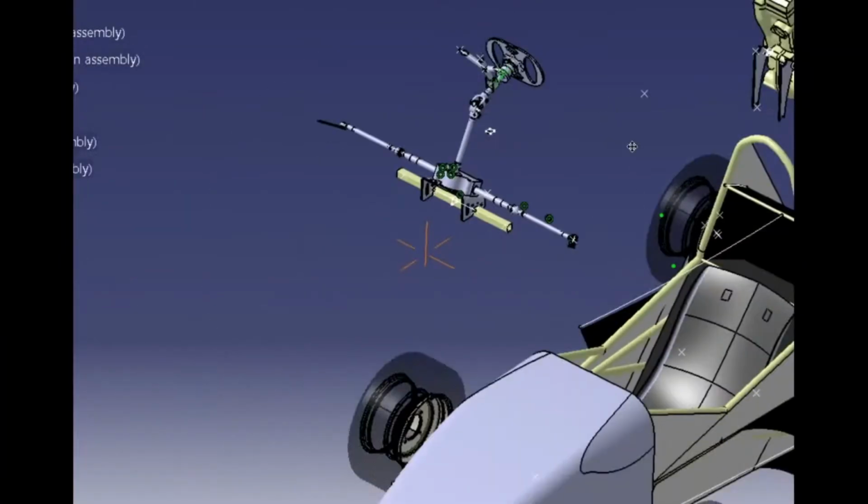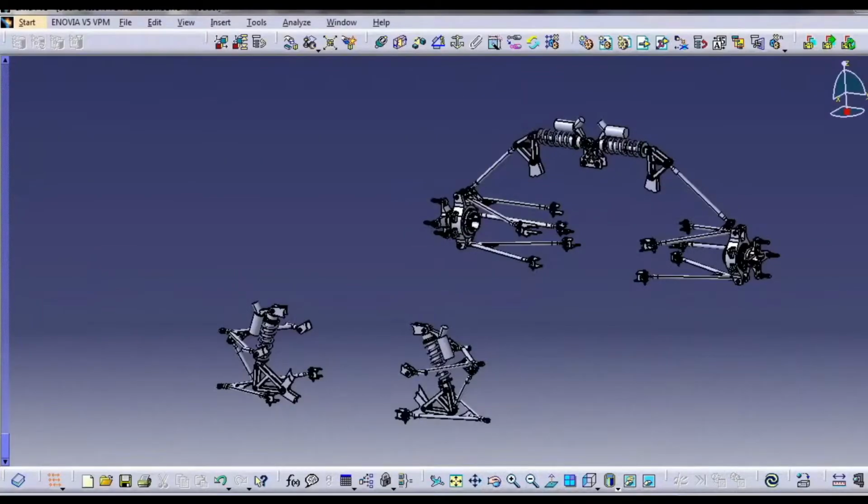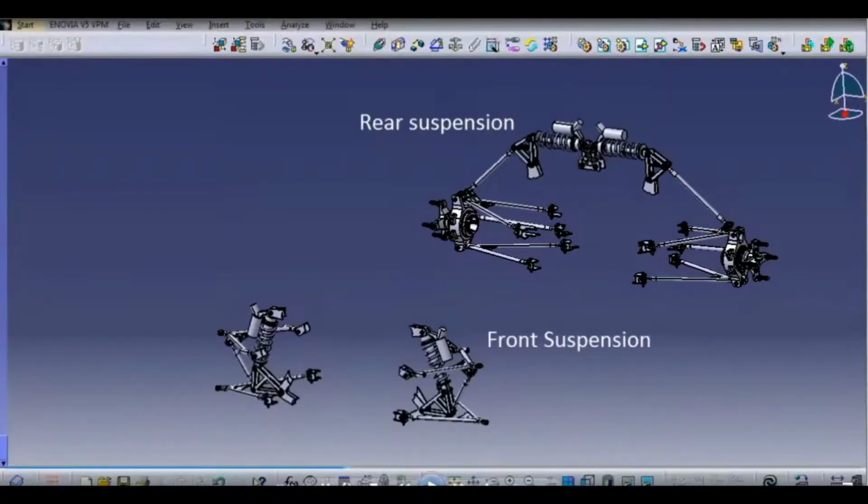After seeing the steering mechanism, let's move on to the suspension mechanism and how it is designed. The main focus while designing the suspension system should be to keep it as simple as possible and reliable, to reduce the unsprung mass and CG height. On the screen, you can see the suspension of our vehicle, both the rear and front suspension system, pull rod and push rod geometry.